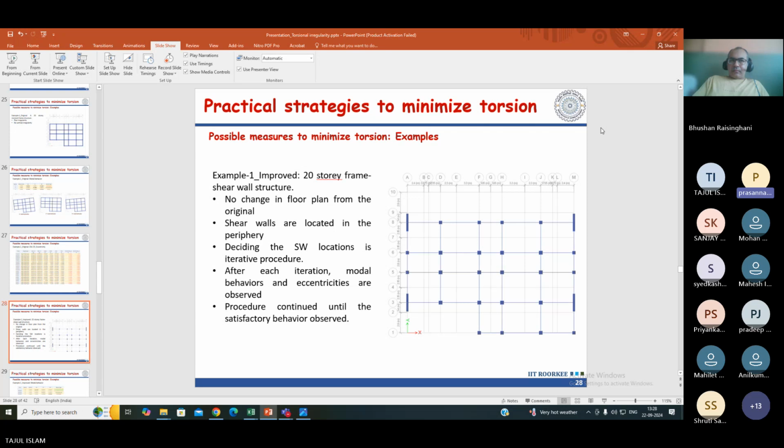Your reinforcement will be designed based on the moment and shear, not on the torsion forces. In the model, in the software, torsion will be there. In the wall, also, torsion will be there. What you are trying to say is that we are designing for the principal directions, X and Y, and the twisting of the column is not considered in design. That is what you are suggesting, right? The software will not take that. So what provision do we have, that whatever additional moments are coming are converted into shear and moment? Sorry, that shear will take the form of an additional moment to be taken by the column.